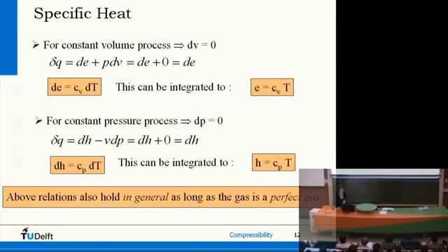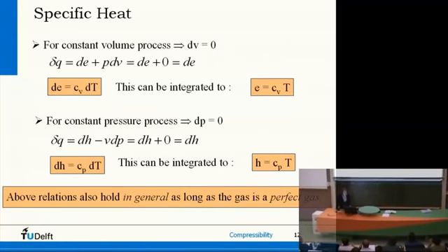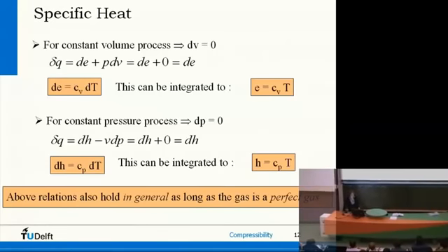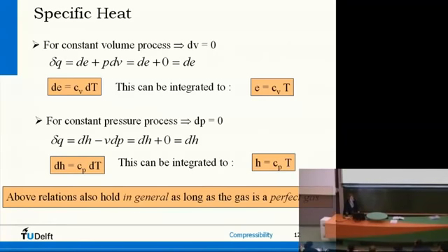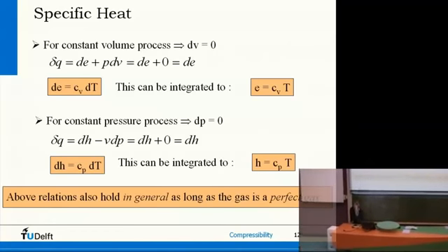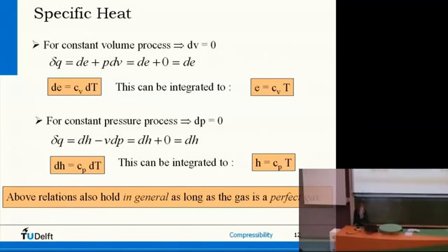Now we'll go back to this form of the first law of thermodynamics, right? I just showed you earlier that dQ is equal to dE plus PdV. Now for this one we choose the constant volume process. In case we keep the volume constant, dV is 0, no changes of volume. So I don't have any work done at the boundaries, and I just have that changes in my internal energy are directly equal to heat added or subtracted from the system per unit mass.